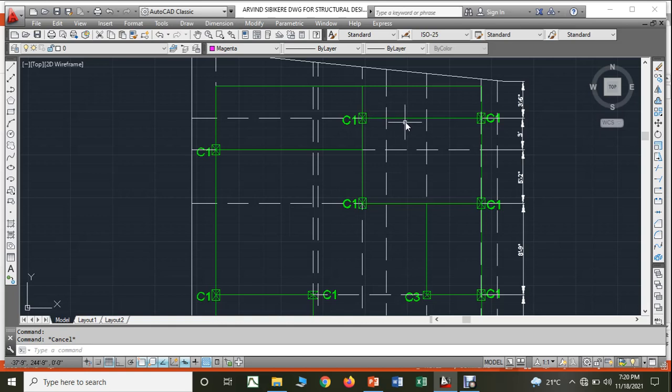It means whatever beams this column has, both are main beams. It means it is going to receive a somewhat large load itself. And not only that, you can see here this entire slab load will be transferred to these columns, and finally again that will come to this column only.